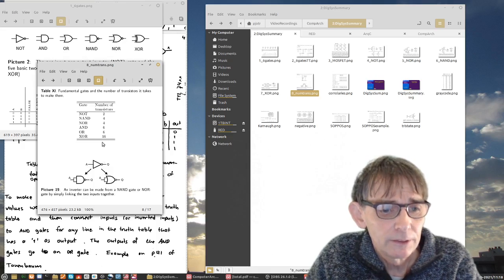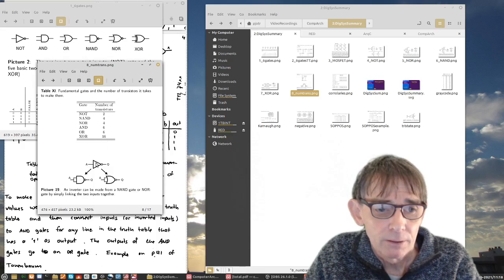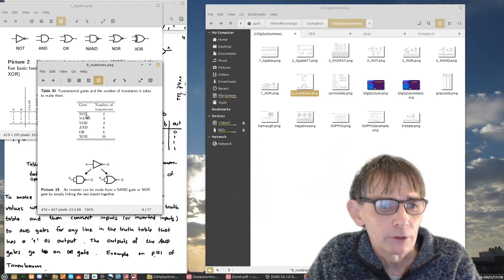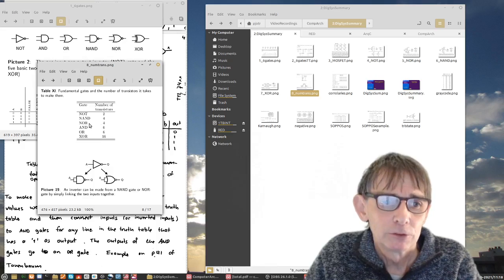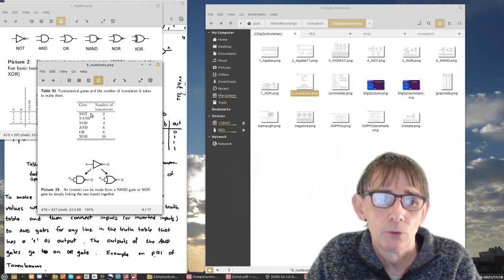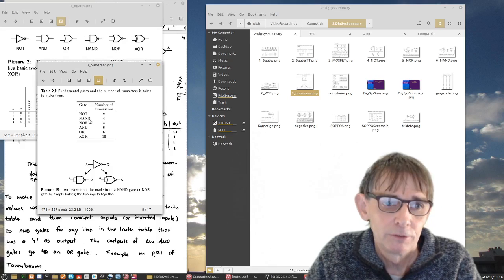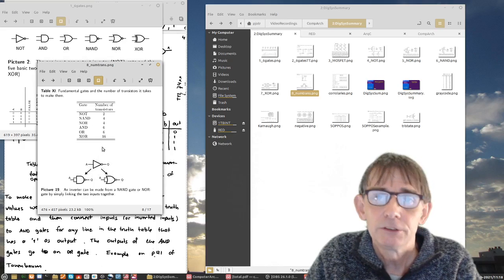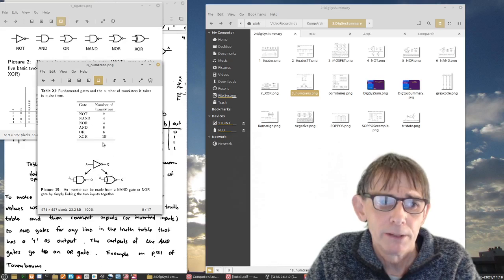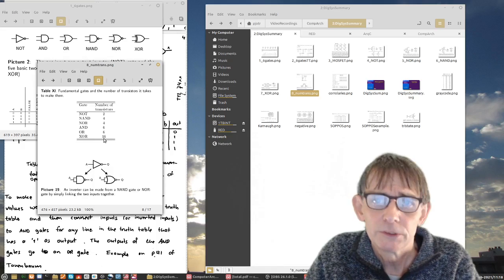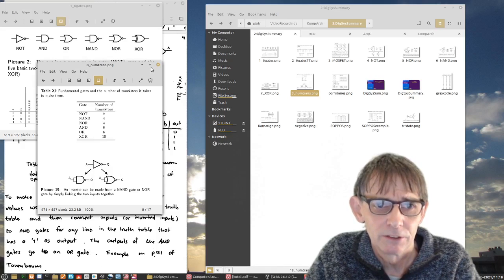In this case, we can get rid of the NOT gate, but maybe you don't always want to do like this. So the thing then is, because the AND and the OR you don't need, because they can be made of NAND and NOR and a NOT, and the NOT can be gotten rid of if you don't want it by this technology. So in principle, you can make everything by NAND and NOR gates, which is a nice, interesting thing to do.